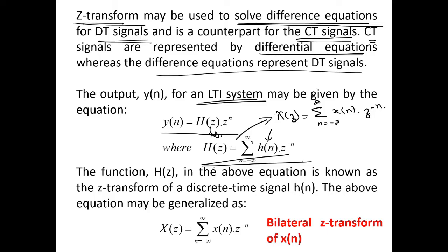So yes, Manibalan, thinking something? Okay. So this equation is the generalized equation of the Z transform. It is a bilateral Z transform equation. Why bilateral? It is present both in the negative time domain and also in the positive time domain. So can anyone tell me the beauty of this equation? There is a beauty in this equation. What is that beauty? Input output relationship for the transform.